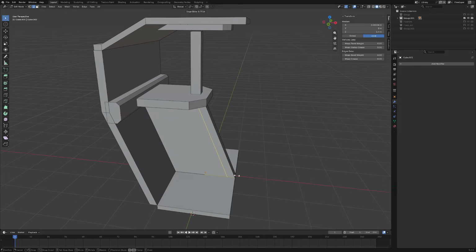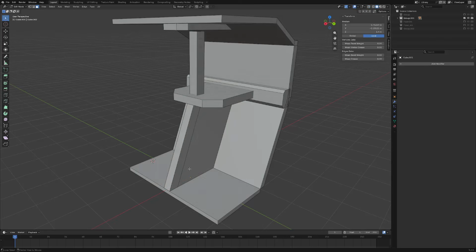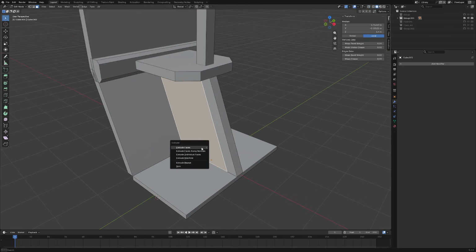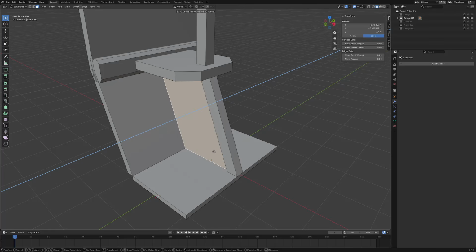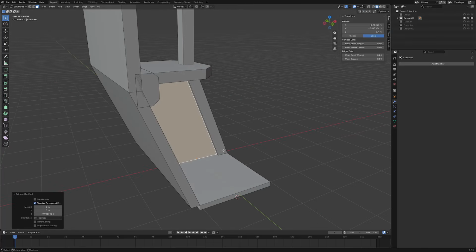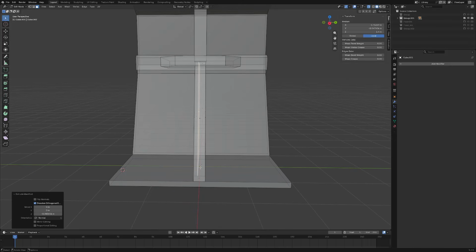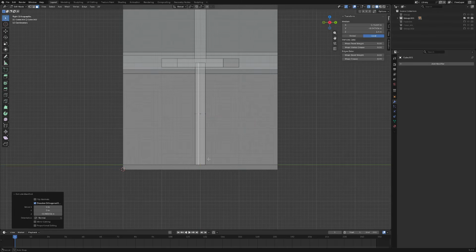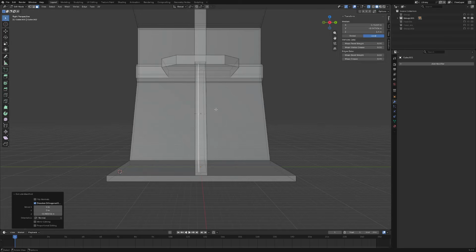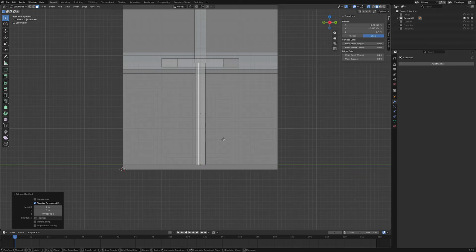Maybe we can do a loop cut. Press E and F, Control R to loop cut EF. And now you can get in here. You can see this is okay-ish, but I can Alt E, through manifold, push that in a little bit. Maybe we want a little bar there or whatever. We can do that. It's not on this side. If our origin point was set correctly here, which hopefully it was, we can just symmetrize this if we want.